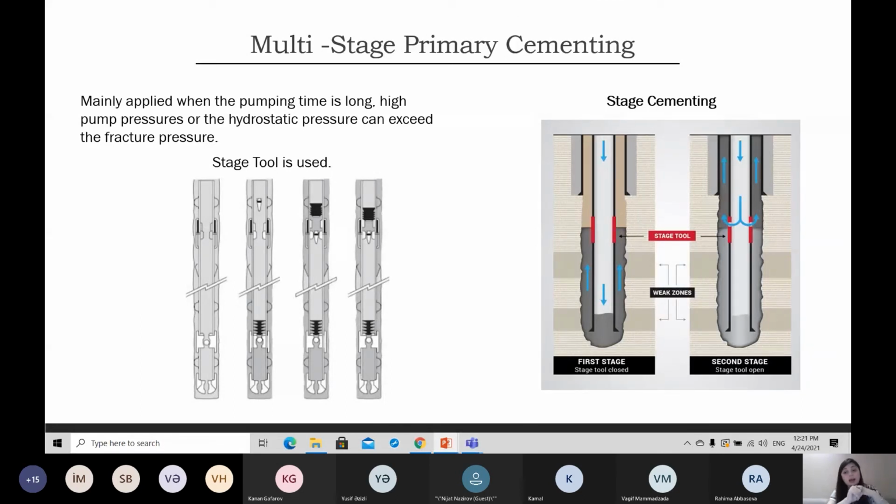First, as a liner, so in liner, top of cement is at the liner hanger, right? The job behaves like a normal liner job. We are pumping through that. We are cementing the annulus till the stage tool. Okay, and then we are waiting for 24 hours, 15, 16 hours, it will depend on the lab testing. We wait till this slurry loses its hydrostatic and it is getting set, it is getting hard. In this case, when we cement the upper section, we will not have any hydrostatic effect in the formation below, right? There will not be frac gradient issue because this is already solid at the bottom and it will not pass this hydrostatic.